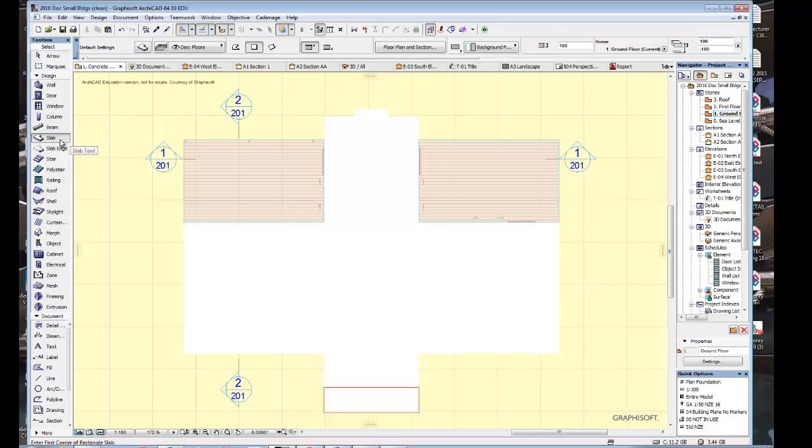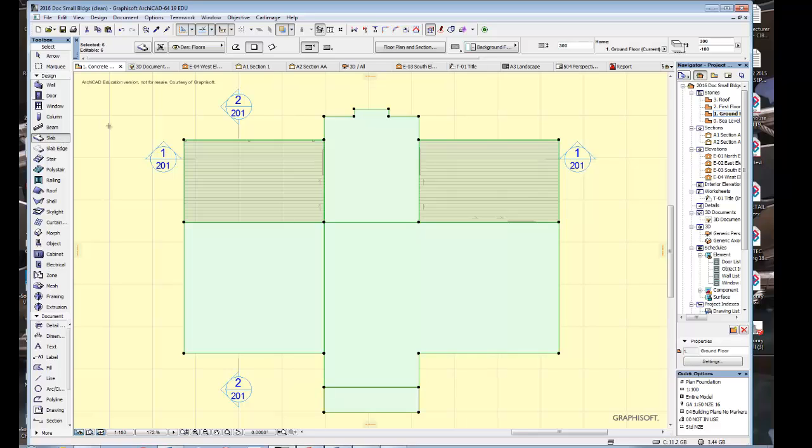So what I'm going to do is go to the slab tool and just select them all, and you can see that we have some 1, 2, 3, 4, 5, 6 slabs. 2 are for the deck. The one at the front we used for our subfloor framing, which you did last week. And our concrete slab, even though the author initially drew this as 2 separate slabs, we could just draw it as one. The one at the front is an entrance slab, so it may help you to just check that and have a look and see what way the slabs are drawn in your model.